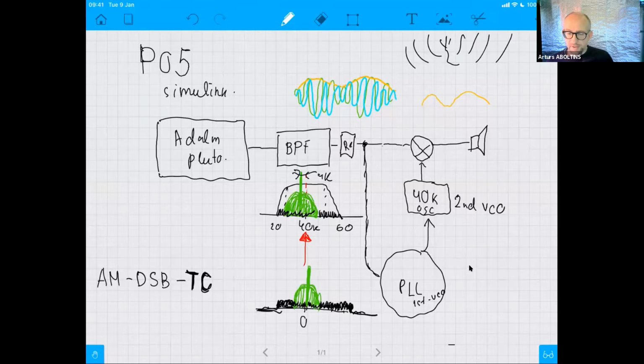In fact, this is two PLLs, the so-called Costas loop, and it's possible then to not use this real part and synchronize to both, this blue and green, but then it's much, much more complex and requires much more tuning, let's say. And some people were not even able to run it and were disappointed. Well, not easy.